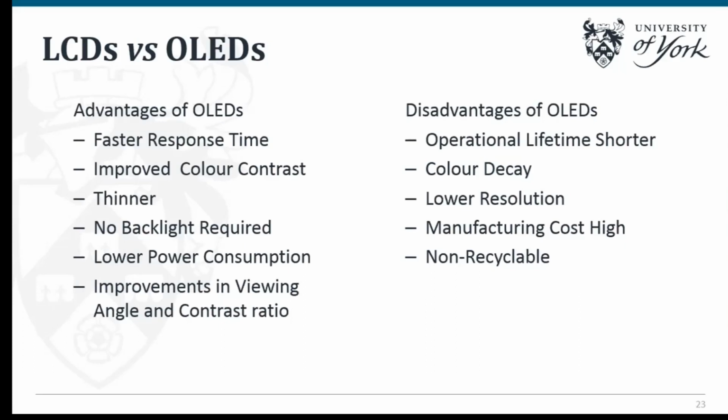Which leads to the second major disadvantage of OLEDs, which is color decay, because your blue OLED in the pixel is going to decay at a faster rate than your green and red OLEDs. So you're steadily going to have your color shift more towards those two and lose the blue.